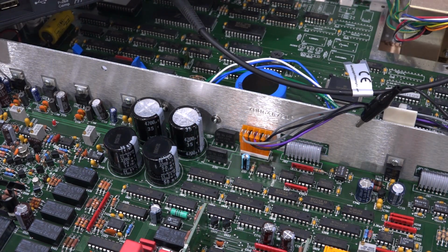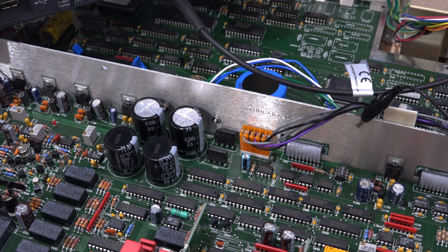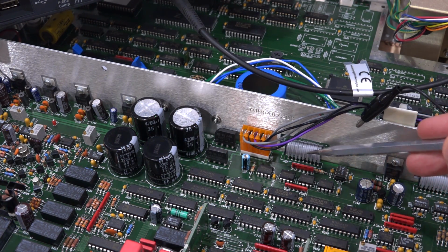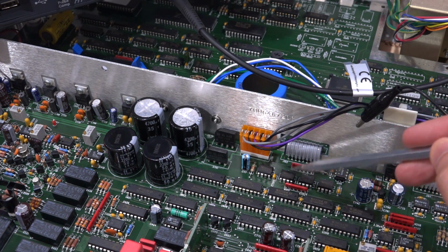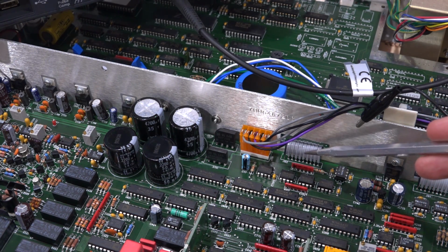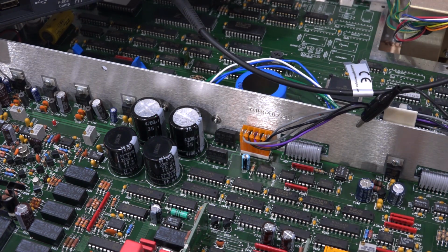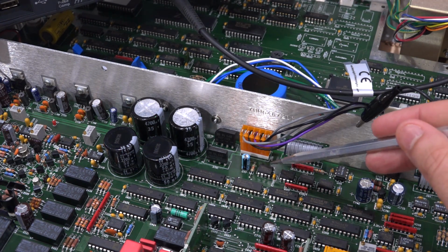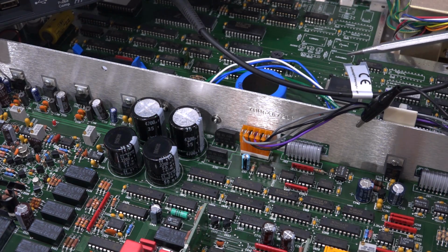So I think I may have found something. I started digging around at the digital interface side. If you look here, here's one of the ribbons coming from the digital side. And we have 1, 2, 3, 4 optoisolators, which are connected to this ribbon in one way or another. And this is what isolates these two halves from each other. So I basically started looking at the signals coming into these, making sure that there is digital activity from this side trying to feed to this side.